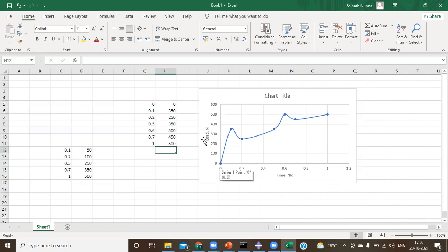Initially what I considered is a heavy vehicle came on my bridge, then a low grade vehicle, and again a heavy vehicle, and again a super loaded vehicle, a heavy vehicle with high load and again a super loaded vehicle. Like this I have considered it, but here what they are doing is gradually increasing the load. This is what the Newton-Raphson says. It tries to gradually increase the load, and with the support of an amplitude you can vary your load as per your range, as per your request.